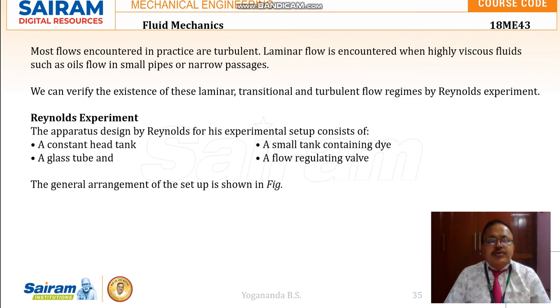Most of the flows encountered in practice will be turbulent. When highly viscous fluids such as oils flow in small pipes or narrow passages, we can find laminar flow. We can verify where the flow is laminar, where it is turbulent, and where it is transitioning from laminar to turbulent using Reynolds experiment.